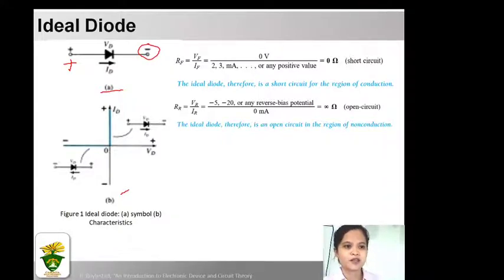To illustrate more, let us draw a switch here. This is a diode, an ideal diode, that acts like a switch. If the current flows in that direction, same as in figure 1A, the switch will conduct. It will close, and the current flows in this direction.